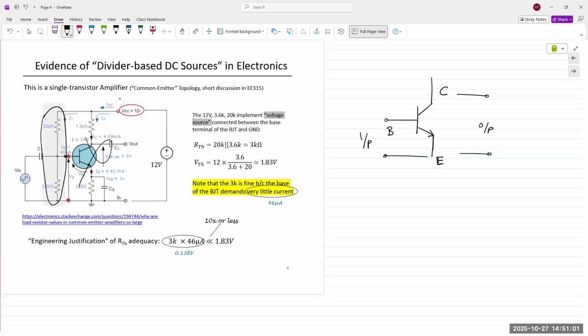And that's what the application is doing here. Still the same concept. It is a series connection of resistors that is creating a voltage divider network. The midpoint of the voltage divider network is creating a small voltage that is going into our amplifier circuit from the left-hand side.